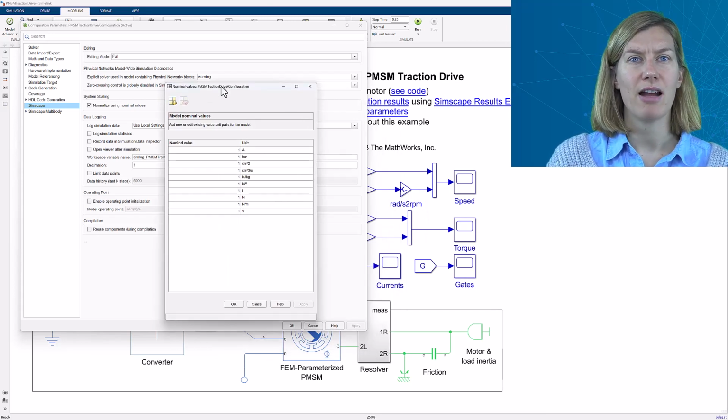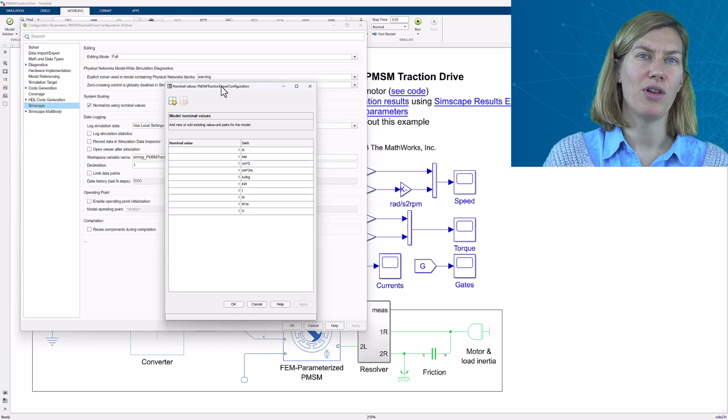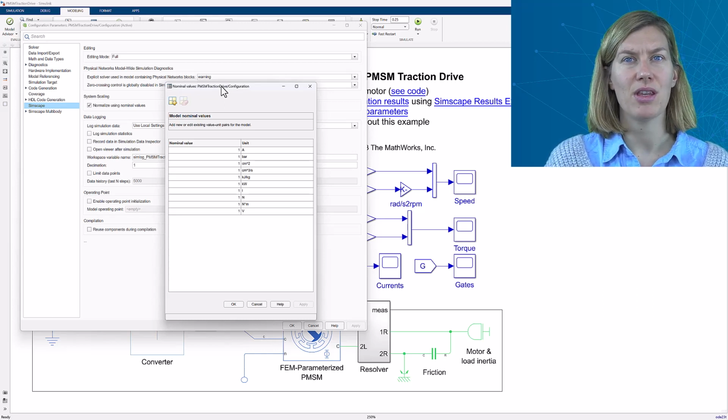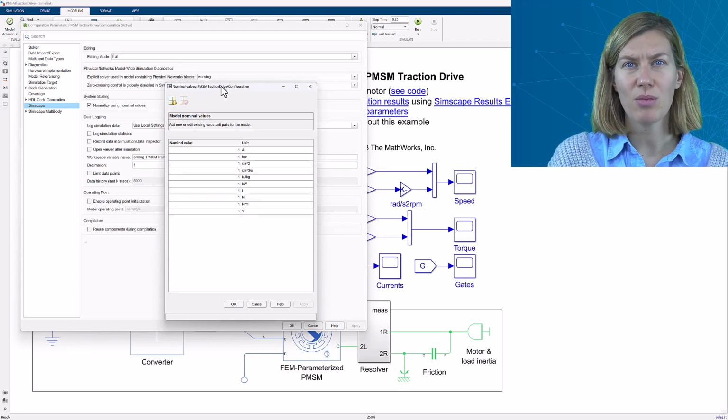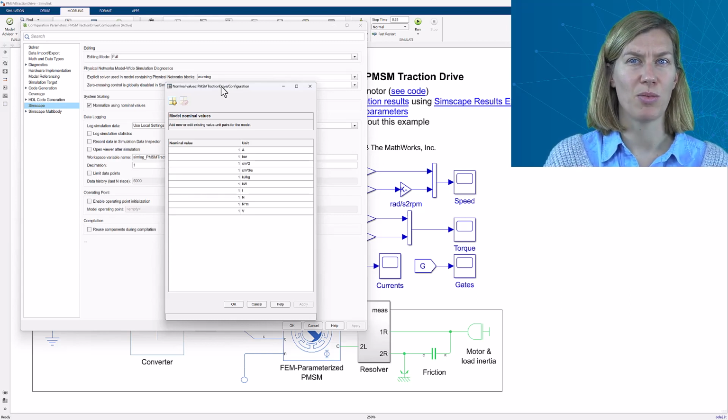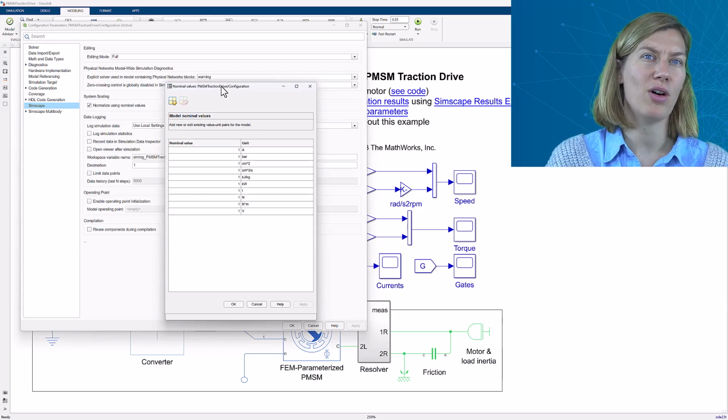When the solver is carrying out the simulation and assessing the results with respect to the tolerance settings, it uses variables without units. And the nominal value is a way of converting Simscape variables to unitless values. Poorly scaled units can magnify or reduce the influence of the corresponding variable. The scale can be either too high compared to other variables, or it can be too small, meaning too close to the actual absolute tolerance value. So for more robust performance, it is beneficial to have all scaled Simscape variables be of a similar magnitude.